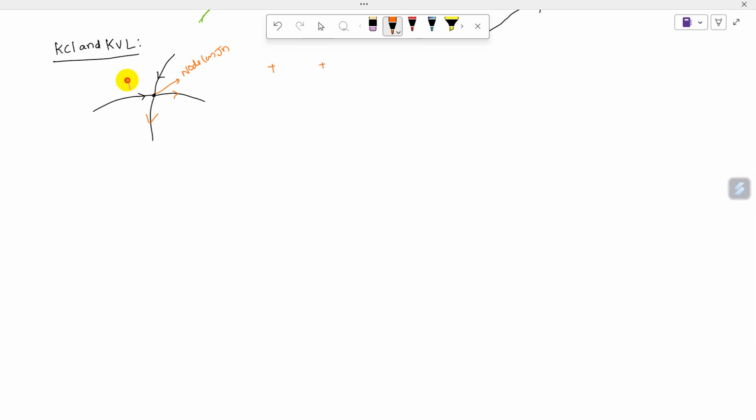So consider this is I1 current, and this is I2 current, and this is I3 current, and this is I4 current. So all current summation I1 plus I2 plus I3 plus I4 should be equal to 0. Mathematically, if you consider all positive values, it should not be equal to 0, which means certain currents definitely have a negative sign. Which one has to be taken as negative?